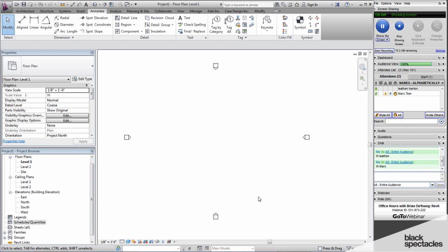to floor. The reason that the architects typically model columns spanning multiple floors is because the architects typically start their model first, and it's typically at a rather schematic sort of level. And so we use architectural columns, not structural columns, because we just want to see something in our model. And it's just a whole lot easier if we just have a column go from level 1 to 10, rather than have it by floor to floor to floor.